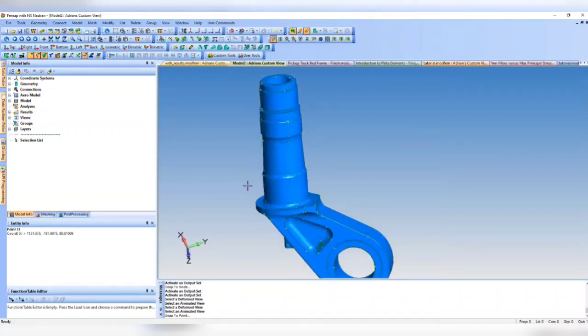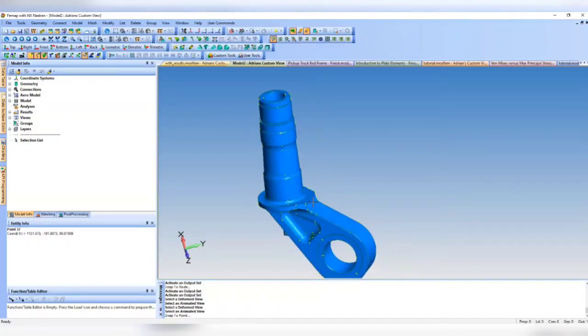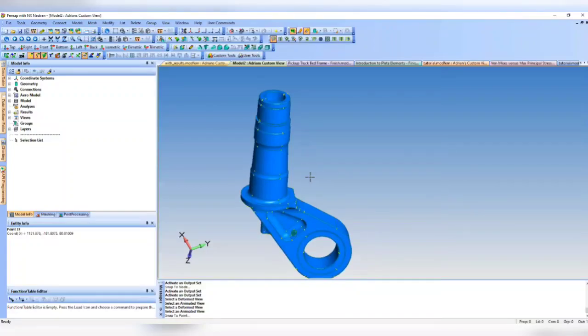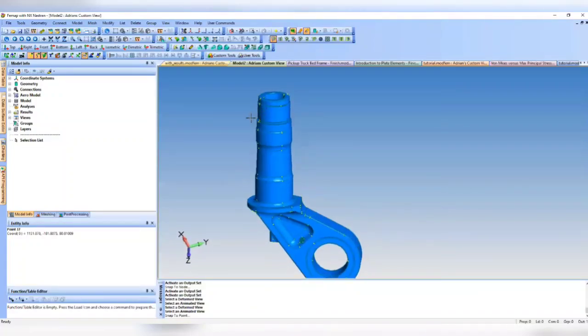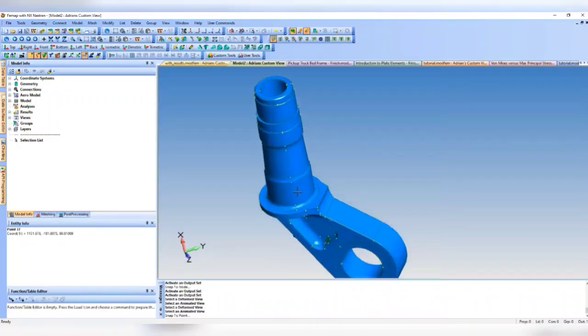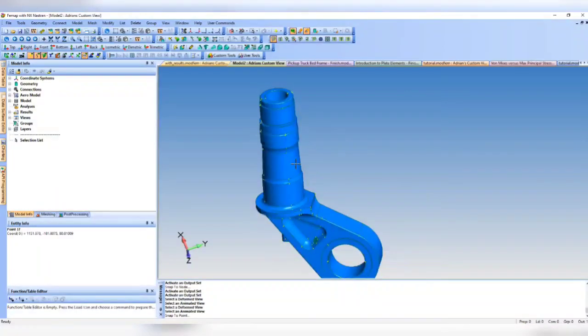So I'm an analyst and I get this CAD and they want me to analyze this component. How am I going to analyze it? In this case, we're going to go very simply. We're going to model it with 10 elements, which are 3D elements. Typically in aircraft structures, for the most part, we don't really deal with 3D elements too much because we're typically dealing with skins and stringers and frames that are more 2D type structures. But I just want to go over the processes and flow when analyzing a structure.